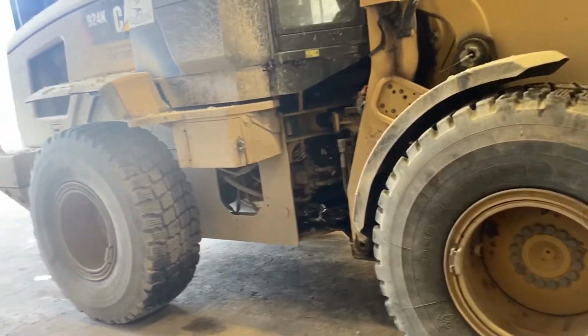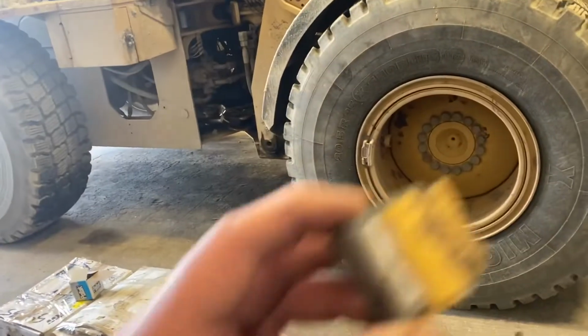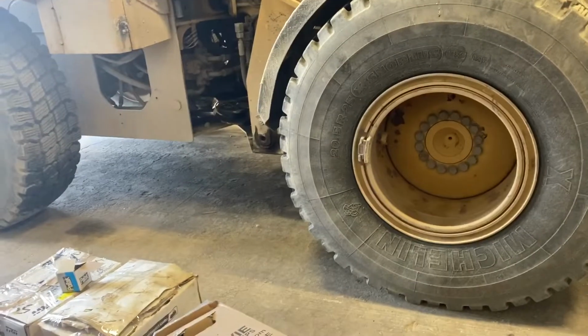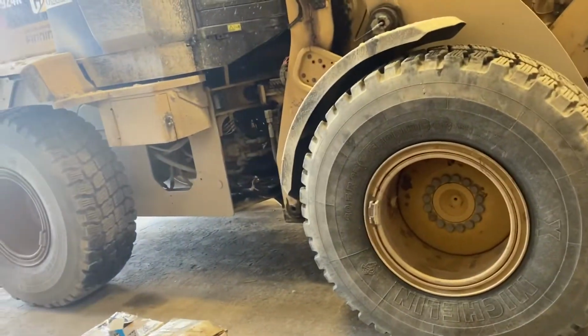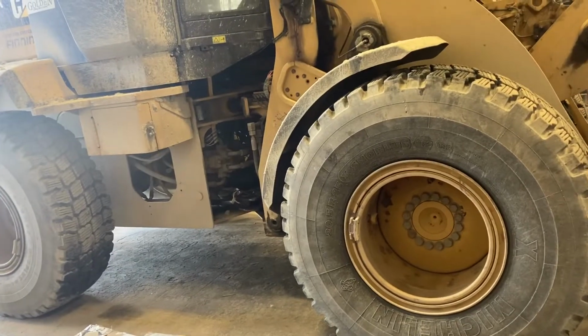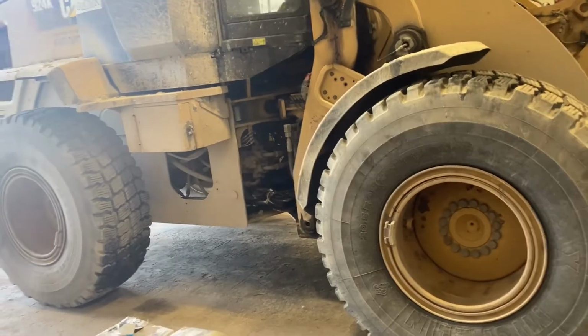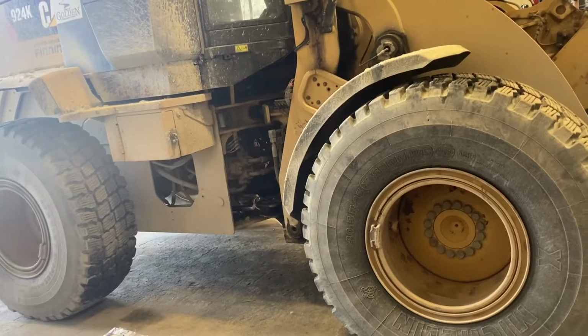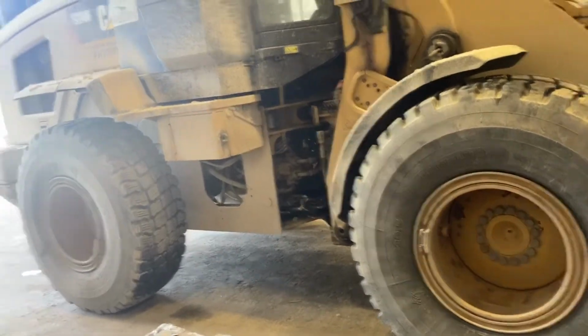So if it's intermittent like that, you're probably going to be changing this. Especially if you do your resistance checks, you've got a good ground to that, got good voltage. Chances are the switch is good. Chances are you're going to throw one of those coils on there and the problem goes away. So let's look at how to diagnose it now.